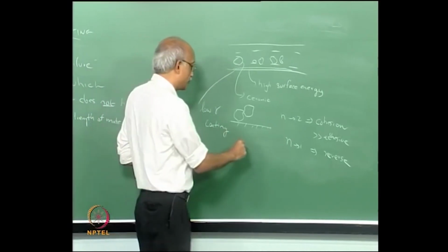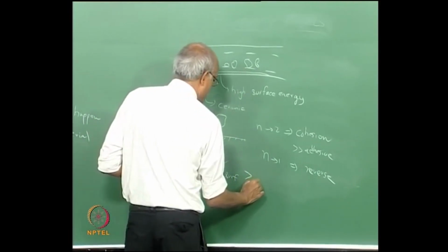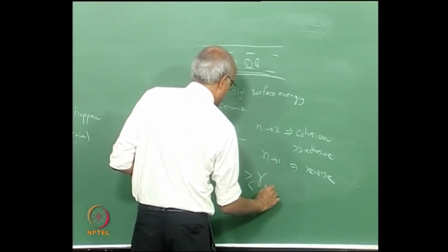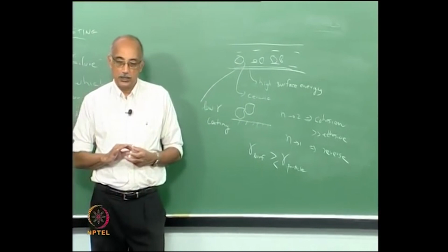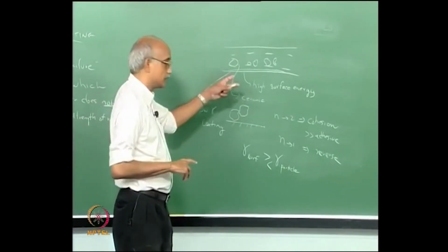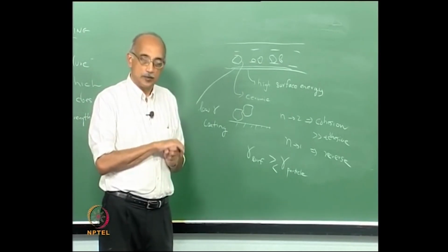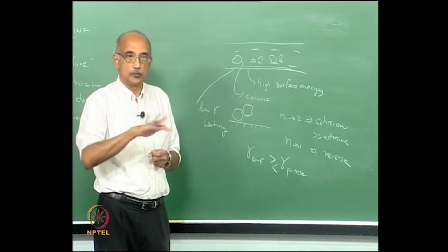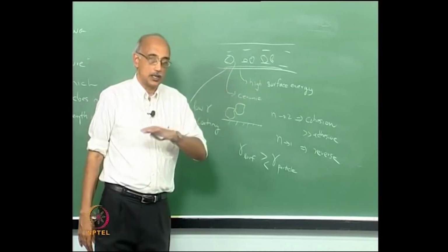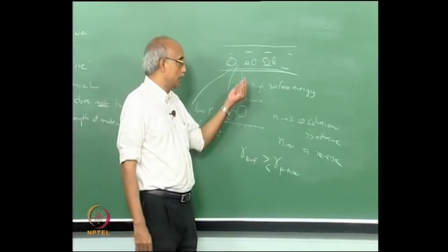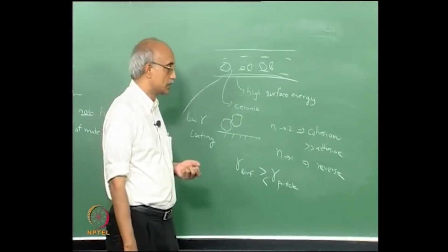Because what really matters is the differential gamma of the surface: is it greater than or less than gamma of the particle? You want to design the system in such a way that the surface on which you do not want material to accumulate always has lower surface energy compared to the surface energy of the material that is flowing past. As long as you can assure that, you know that the tendency to attach to the surface is going to be minimized and the particles are going to want to stay in the flow of the slurry or suspension.